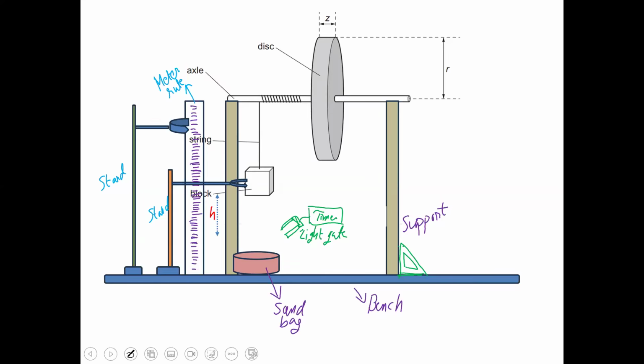Normally, they believe that everything which can create trouble, like a moving disc, can fall. So you have to secure the whole apparatus. If it falls, it can create a big problem. It's a heavy disc. So you should use a safety shield, and people should be away from this apparatus, not in front of it. They should be on the side.